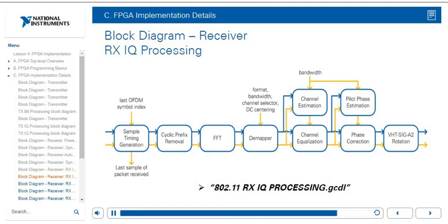The channel estimation is computed using the second LLTF OFDM symbol for 802.11a and VHT LTF for 802.11ac. And the channel estimation block is implemented in a parallel path to minimize latency to the data path.